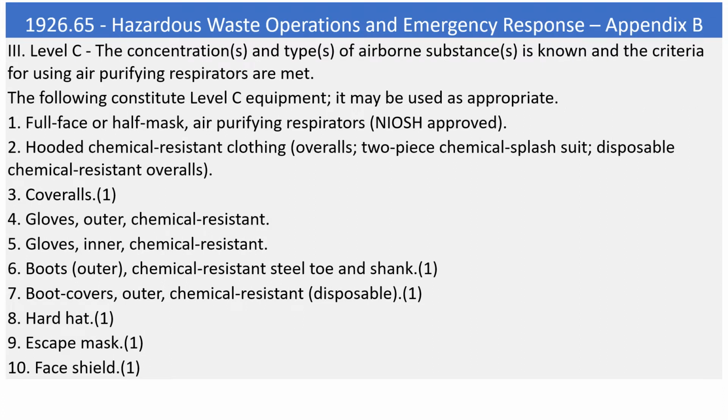3. Level C. The concentrations and types of airborne substances is known and the criteria for using air purifying respirators are met. The following constitute Level C equipment. It may be used as appropriate. 1. Full face or half mask, air purifying respirators, NIOSH approved. 2. Coated chemical resistant clothing, overalls, 2-piece chemical splash suit, disposable chemical resistant overalls. 3. Coveralls. 4. Gloves, outer, chemical resistant. 5. Gloves, inner, chemical resistant.